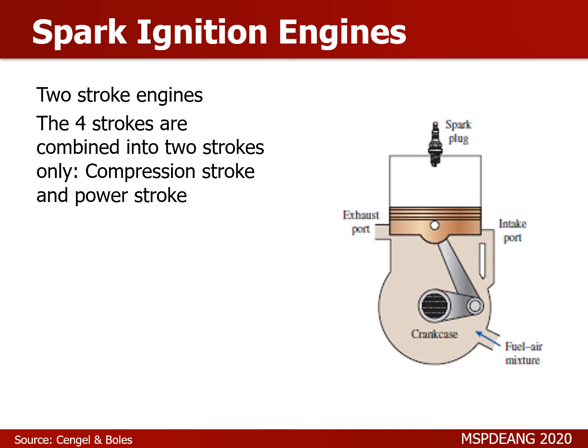When you do your exhaust stroke together with your compression stroke, you might expel some of your fuel-air mixture. That is why sometimes, with lawn mowers, you smell gasoline. So that is one of the reasons, due to the inefficiencies of combustion of these two-stroke engines.